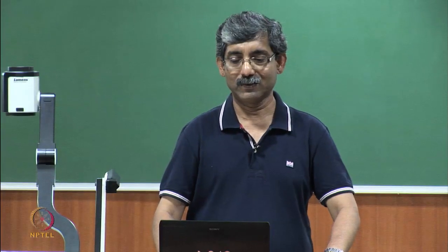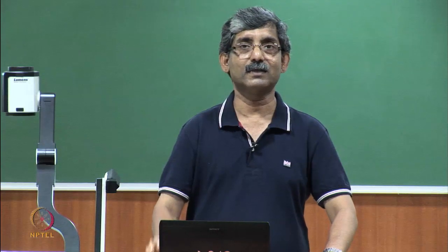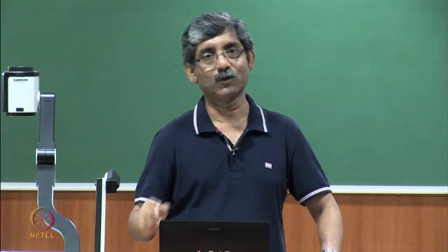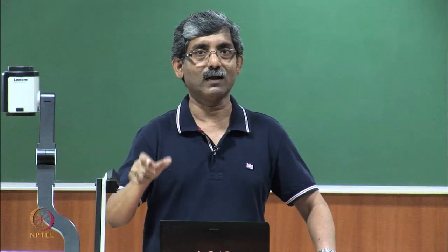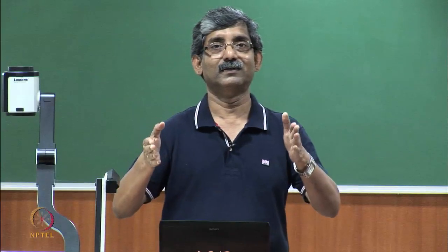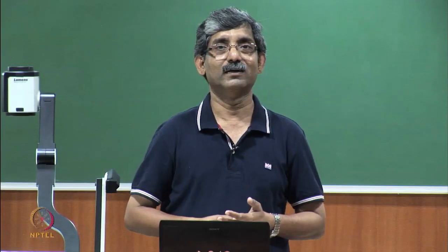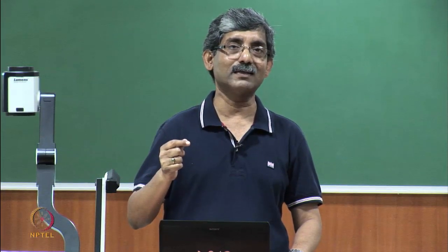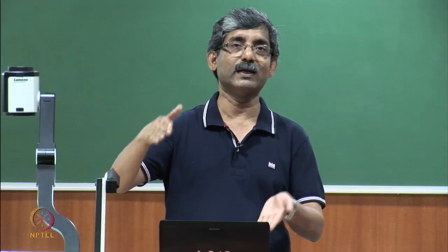So, it will replicate the winding method, okay, and then give us the idea about the tension required for a particular breakage. So, it provides conditions somewhat similar to the actual processing of yarn during winding, warping, sizing. So, knowing only the yarn strength in static mode will not help, because that will give us the test value of a very specific length.